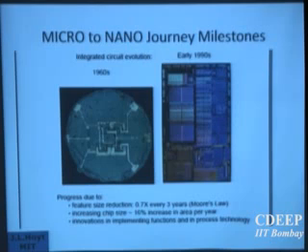So what is the most important law? What exactly is he trying to say? In a word, since you are going to follow electrical engineering later, and most of you will be using chips left and right, what Moore says is that the size of a transistor will reduce every generation by 0.7. And if one side reduces by 0.7, the area, with 2 sides, will be 0.5. So that's why that number becomes double, 0.7 into 0.7 is essentially 0.5. So you say every year it will start doubling because in the same area you can now put double the transistors. That's what Moore's law was saying.